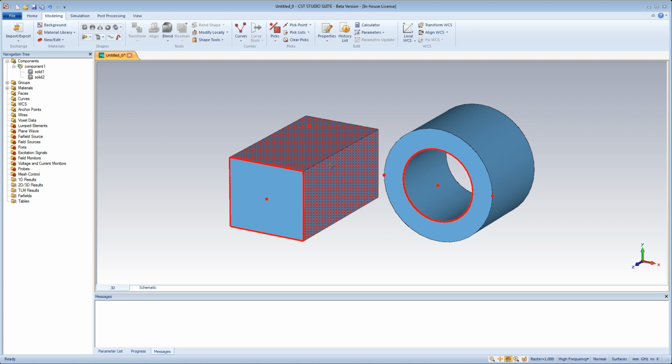The pick operations for selecting points from the model are also valid in the interactive shape creation modes. Here, whenever you are requested to double-click in order to enter the next point, you may alternatively enter the pick mode. After leaving this mode, the picked point will be taken as the next point for the shape creation. Previously picked points, edges or faces can be cleared by Clear Picks or D.